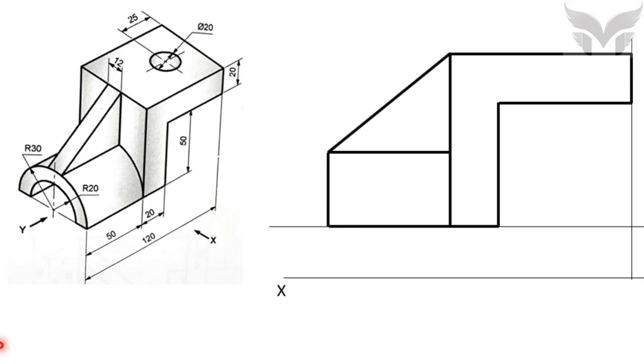Dear friends, till now we have tried to show the details which we can see from front. Now it's time to look at the object more carefully and look for the things which we can't see from front, like this semicircular slot inside a semi-cylinder. Also the circular hole at the top. These 2 things which we can't see from front, we have to show by using dash thin or dash thick line pattern, which is most popularly known as hidden line pattern.